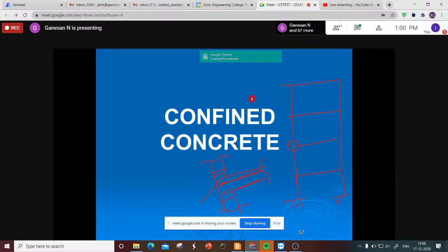These ties will improve the ductility, the structural integrity, and the dimensional homogeneity of the composite, and the spalling of concrete will never take place. Because of that, the entire concrete will act like a single material, and that will redistribute the bending moment to other places like this. Then that will prevent the damage to the joints. They are very important. So that's what I want to convey.